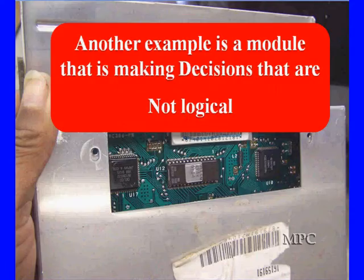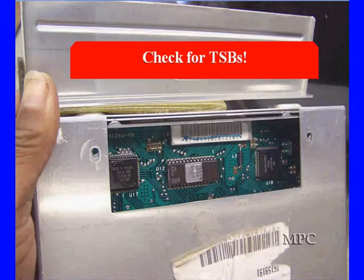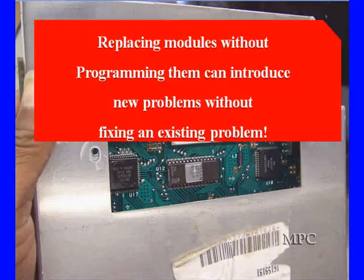The module that is making decisions that are not logical. Well, check for technical service bulletins. We cannot say it enough. There are some cases where nothing but a technical service bulletin will replace an unlimited amount of information. Other cases, you've got to remember something. When replacing modules without programming them, you can introduce new problems without fixing an existing problem. Let's say that again. Remember, replacing modules without programming them can introduce new problems without solving it.